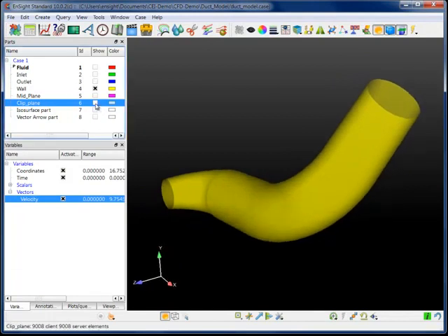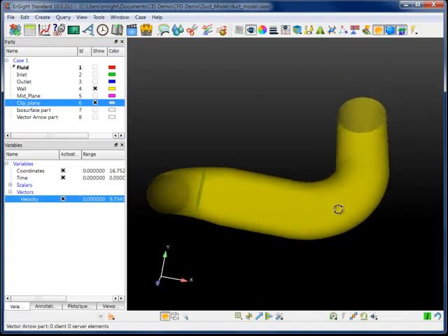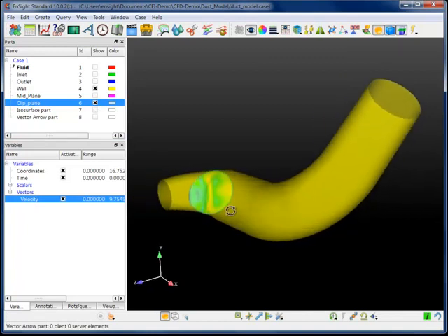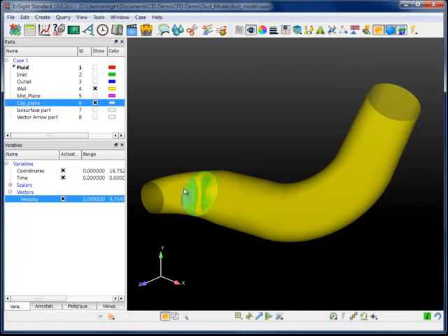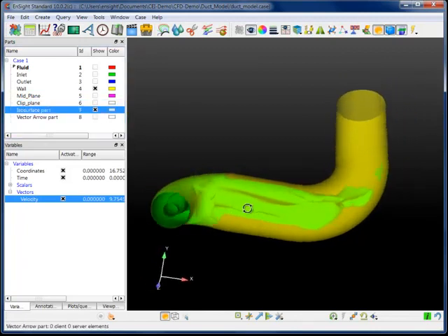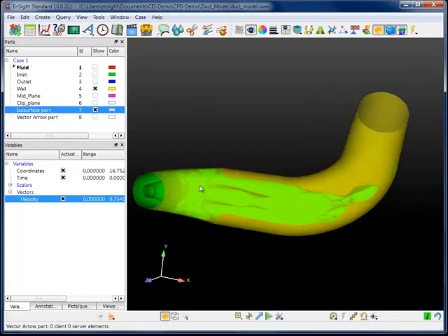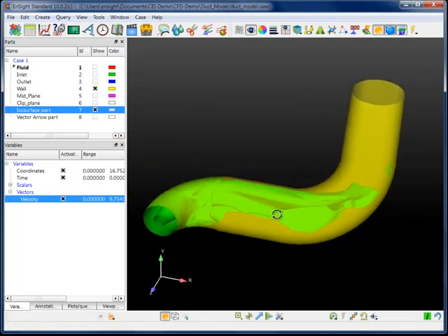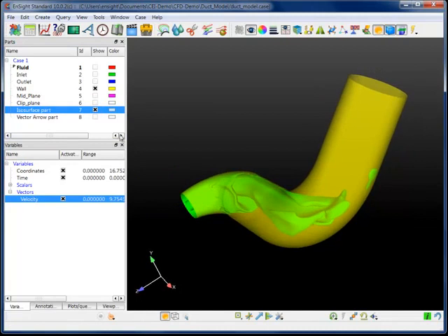If I show you what a clip plane looks like, you can see a little bit of the non-uniformity in the flow, but it's really just looking at a particular plane, and I can make other planes that might show it a little bit more or less. I could even turn on an ISO surface part to try to understand the flow, but again, I'm only really looking at a single value at a time. And this is where volume rendering comes in.